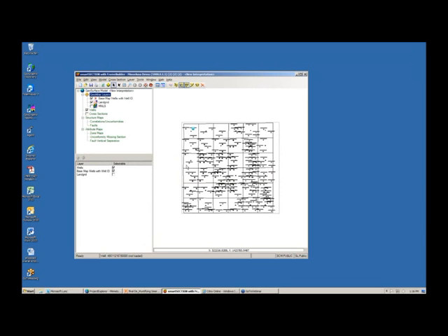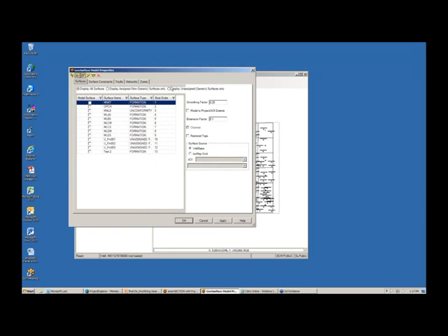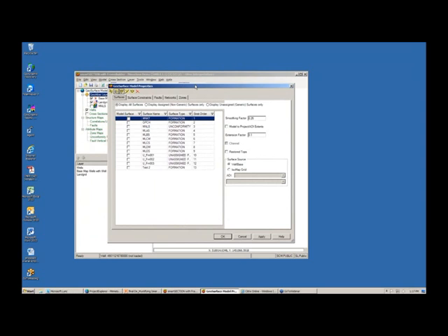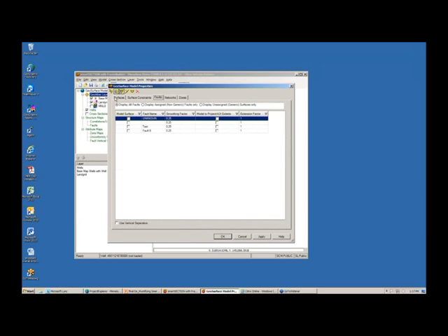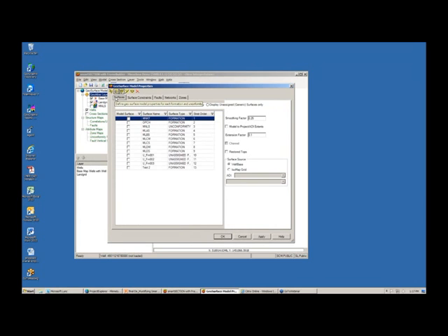Finally, now that we've defined our preferred list of sources and our formations are in good stead, we want to actually select which formations we're going to build our cross-sections on, build our maps on, and actually model. So we're going to go up to the GeoSurfaceModel Properties tool. This is probably the most important tool in all of smartSECTION. So I'm going to click on that. This is where you actually tell the software which formations you wish to model. You can model faults in the Faults tab or surfaces in the Surface tab. Basically, all you do is come in here and highlight the formations that you wish to model.